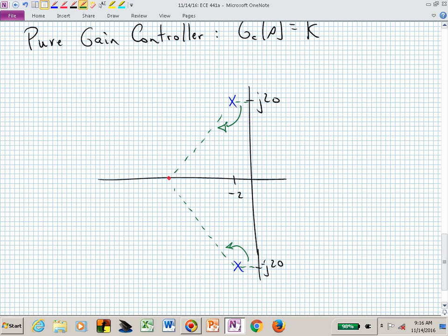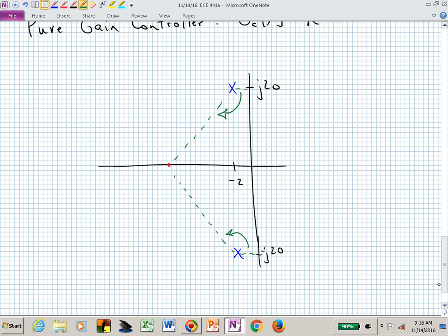But where is the root locus going to be, or what happens? So now we've already done Rule 1, Rule 2, Rule 3. You have these cheat sheets available to you. You go, okay, what are my asymptotes? Do I have any asymptotes, and when do I have interesting asymptotes? When I have a pole zero excess. Do I have a pole zero excess? What is it? 2. So now I divide 180 by 2 and I get 90. I now have 90 degrees for my fundamental angle, and my other one is 270 or minus 90. So I now have plus and minus 90 degrees.